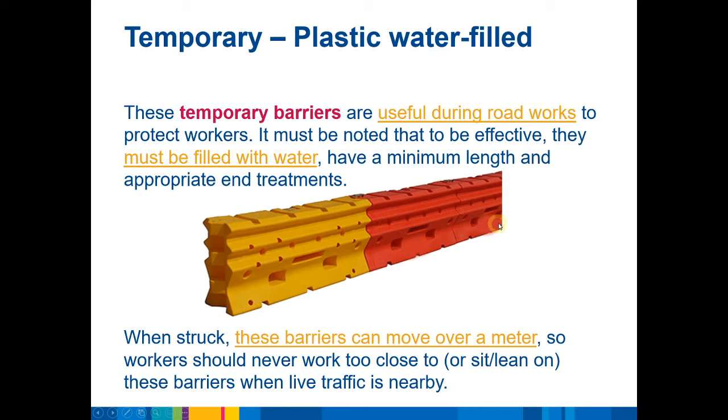Or maybe every second barrier is filled a third to half the way full, and every barrier needs to be fully filled for them to be effective. Putting them up on a road where you've got workers behind them and expecting those workers to be protected without properly filling them is really quite hazardous. In fact, this can be more hazardous, because where the vehicle comes off and strikes the empty barriers, the whole chain of barriers, all linked together, will go flying.